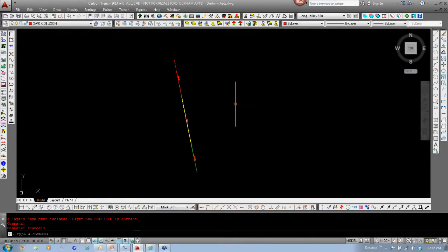And then we have another question: can trench width be based on pipe size? You can, and I think Todd will probably get to some of this in just a minute. I basically created my trench to add 18 inches on each side of the pipe. So as the pipe size increases, that trench width increases 18 inches on both sides. Okay, that's all the questions. That's good.